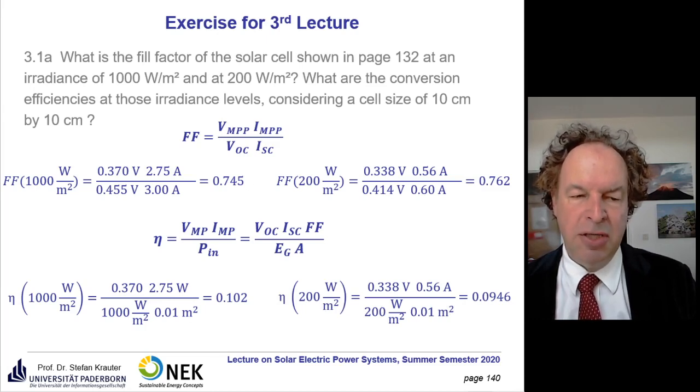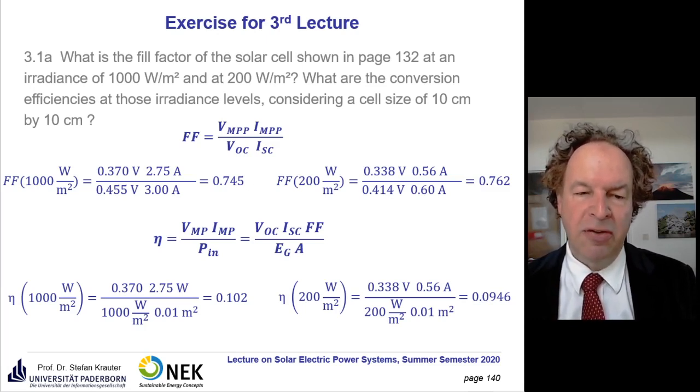That's a pity, because when you have low irradiance, you have additional losses, and you don't get proportionally the power output, you get a bit less. This depends very much on the purity of the materials, because this is determined by the resistor RP, which is bypassing some of the current and accordingly of the power.